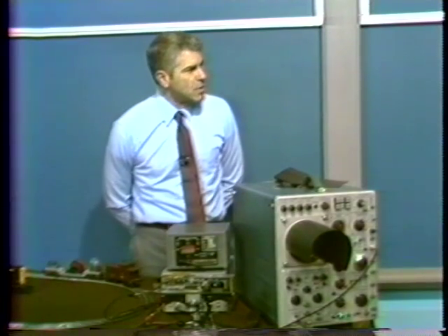And you might imagine when you put those constraints together, you don't end up with the best quality gears in the world. You end up with gears that have a good deal of backlash. You end up with a motor that has a remarkably high friction level. The commutation is not very good, so the torque isn't particularly uniform over the revolution of the motor. There are a whole collection of mechanical kinds of problems, none of which influence the reliability of the system or affect it adversely at all when it's being run in its normal mode. But we see the effects of that on the oscilloscope trace.